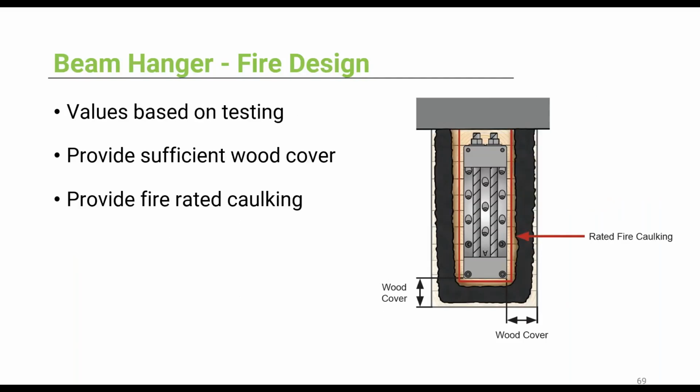It's also important to note that these values are based on the testing done in the United States. By providing sufficient wood cover that's more than the char thickness, we can easily have a fire-rated connection. And it's important to have fire caulking around the connectors, just as we saw from the testing.